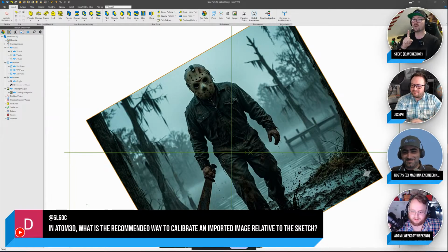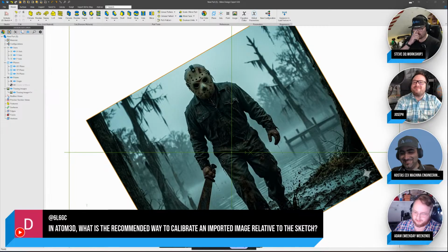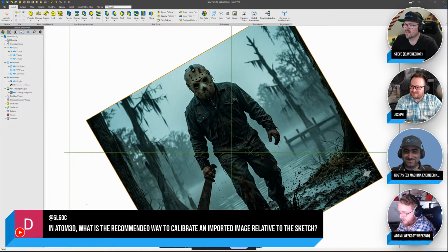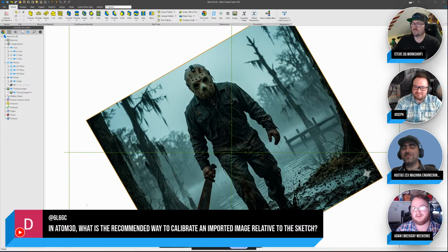As in, please don't use a wide-angle lens, because believe me, I'm a photography guy. I like photography. Please don't shoot wide-angle if you're taking photos to be measured. Use something like 100 millimeters, 70 millimeters. Don't use your 30 millimeter trying to take photos you're going to measure, because you're going to get that difference in perspective. You're going to get a fisheye effect on your product, and it's going to morph the dimensions quite a bit. 100%. Excellent.